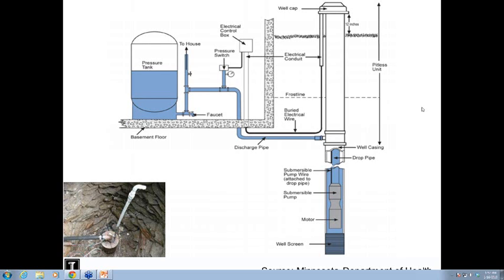And really what you should do is mix your Clorox with water to lower the overall concentration to a few hundred ppm versus 5% or whatever it is in straight chlorine, so that doesn't happen. And that'll be one of the things that we recommend later when we get to that lesson. And so there are differences around the country, just like the